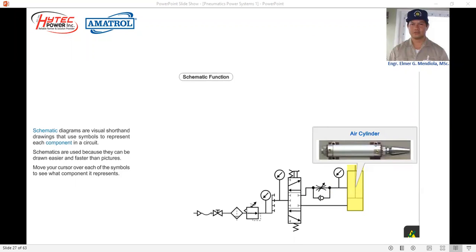After the directional control valve, the pressurized air will then flow to an actuator. The actuator can be a pneumatic motor for rotary motion or a pneumatic cylinder for linear motion. Based on the diagram, a pneumatic cylinder is used. The piston and rod of the cylinder can extend or retract depending on how the directional valve is manipulated.